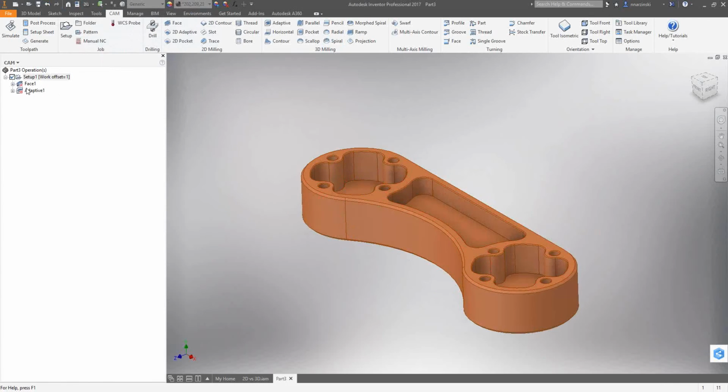so we are referencing that SolidWorks part file, and we also have some red X's over here inside the CAM browser, telling us that those toolpaths are no longer attached to the geometry. So if you highlight them, you can see that they still look like the old part looked like. So the way around that is you just select the setup and click generate. It's going to regenerate those toolpaths to that new geometry.